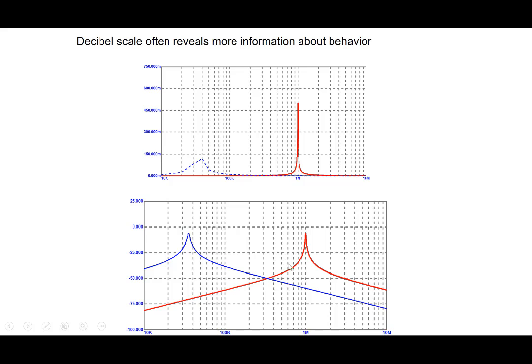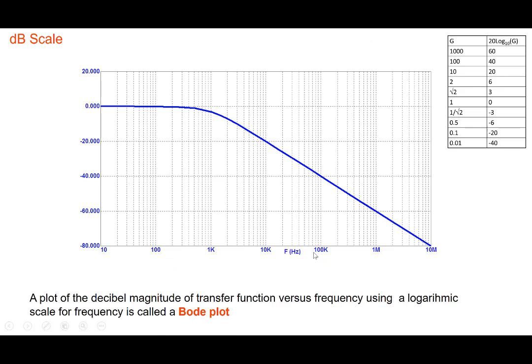So it's continuously reducing, of course. And we can see what the strength of the signal is here compared to the peak value. For example, at this particular point, the signal is maybe 70 dBs below this particular one, and somewhere else you may say the signal is 50 dBs below here. Once you understand what the dB scale really means, then you can easily correlate.